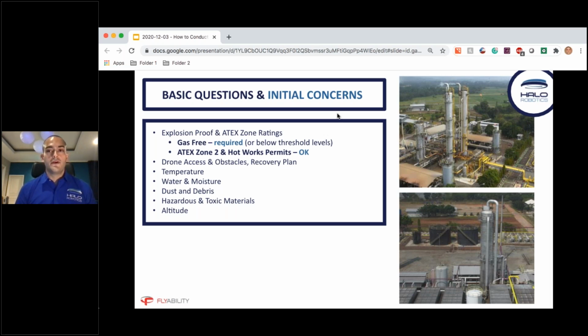However, the good news, and I think it is important to mention, is that drones can definitely be operated in high risk environments, including in oil and gas, and including in clean fuels and LNG, where there are real concerns about flammable vapors. The note is, how do we address that? Basically the environment must be gas free, or at least a gas detection sensor needs to indicate that the gases are below tolerable threshold levels.